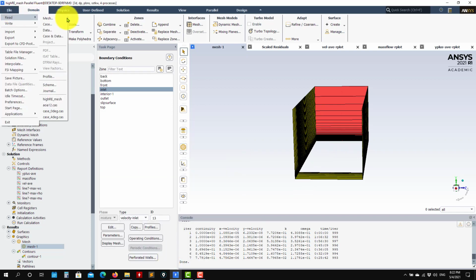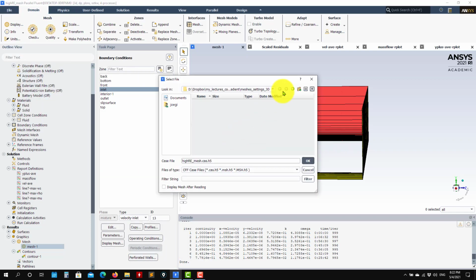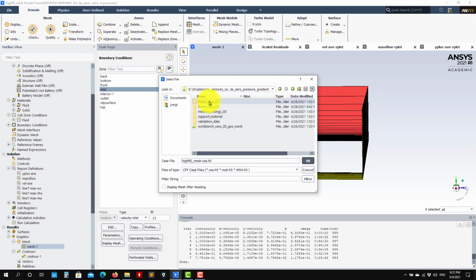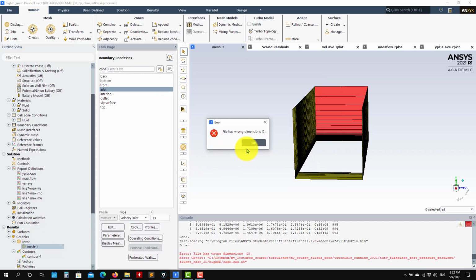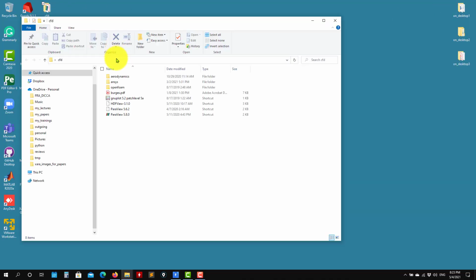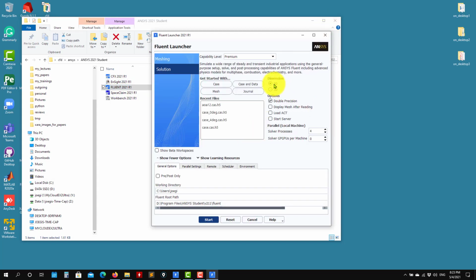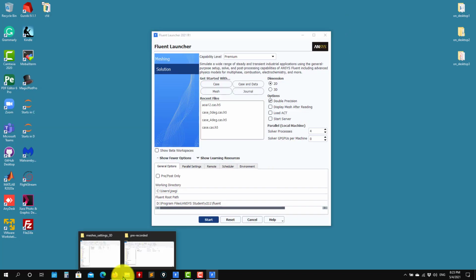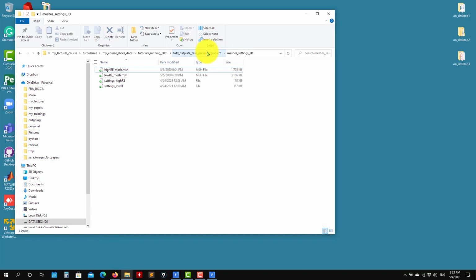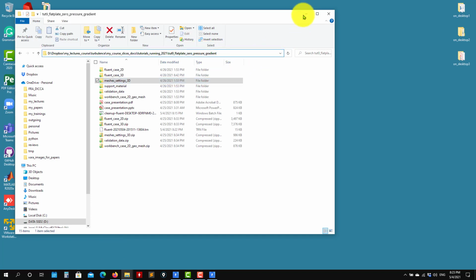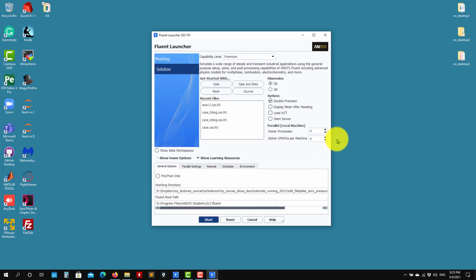And just to show you the difference, let me now open the case in 2D. So we don't have the 2D mesh, we only have the 3D, but now I can open the 2D case that we have, just to show you. So, okay, first it gives me this warning because you also need to launch Fluent in 2D mode. So let me launch another session, okay? But remember to set it to 2D, okay? In the other case it's 3D. Even if you have one cell, you need to set that case as 3D. Now this 2D mesh, let me go here and let me launch. Okay.